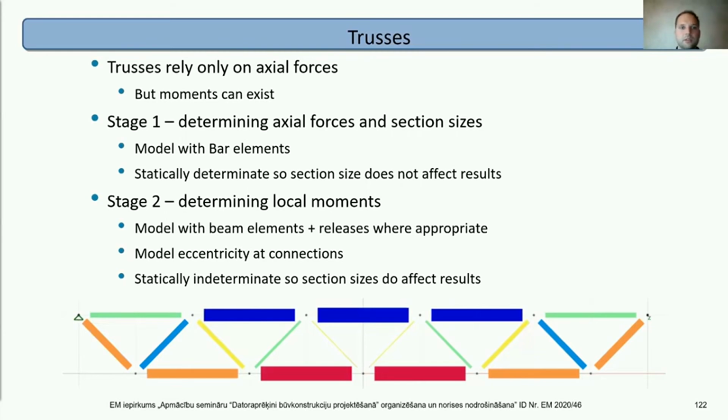Yeah, it's tricky. If it's early stages, you don't know reinforcement yet, you want to make an approximation. You know from the code what the minimum reinforcement is. You know from the code what the maximum reinforcement is. You could say it's probably halfway between the two, and use that as the starting point. It won't give you the end answer, but it can give you the initial answer.